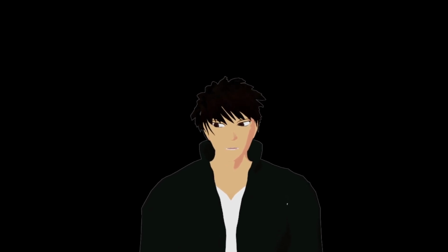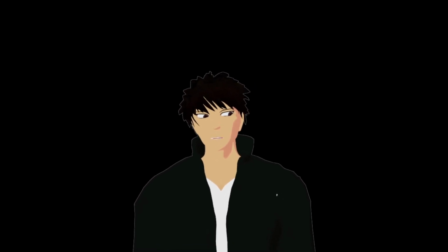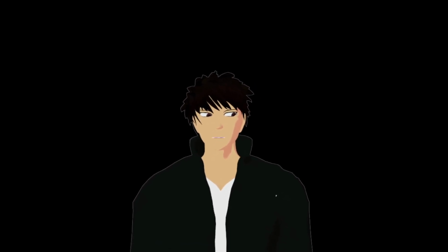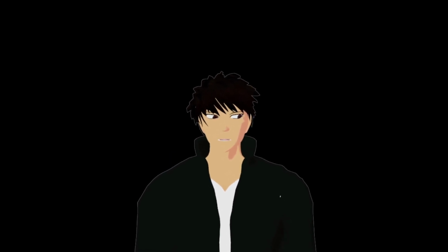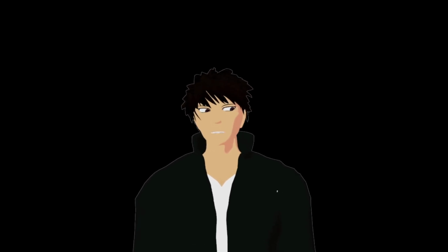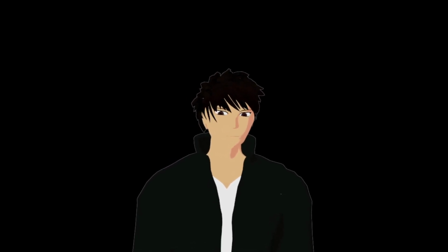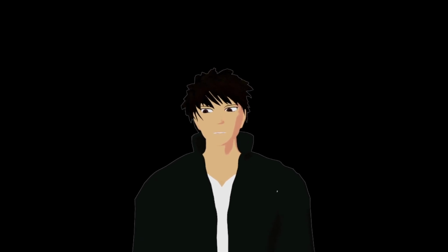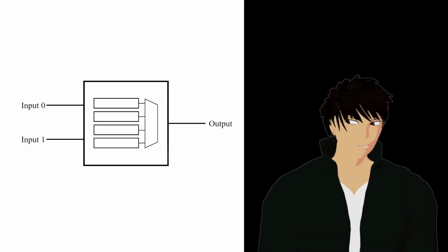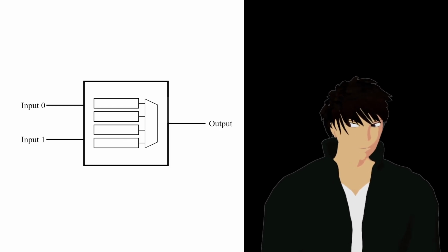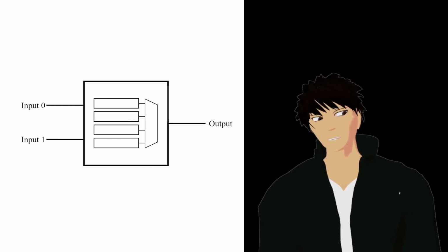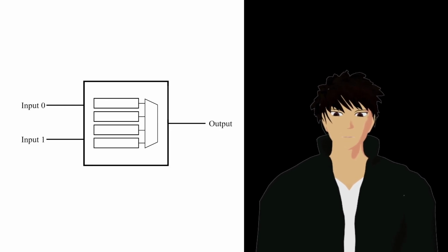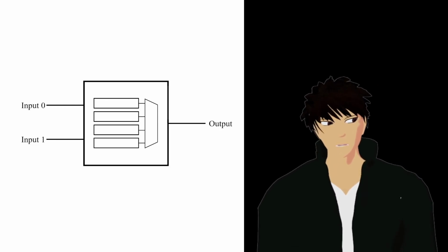Now, the beauty of digital logic, and more broadly in engineering, is that these problems can be compartmentalized. They can be broken down into smaller, well-defined chunks that can be developed separately and then recombined at the end. You can repeat this process until you get chunks that do fit in a LUT. Then all you have to do is combine all these LUTs together into a network that satisfies your original design requirements. That's the second half of the FPGA equation.